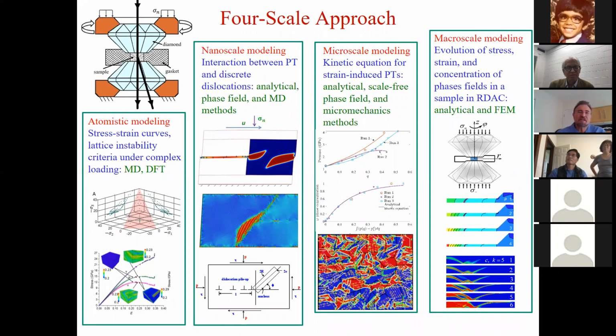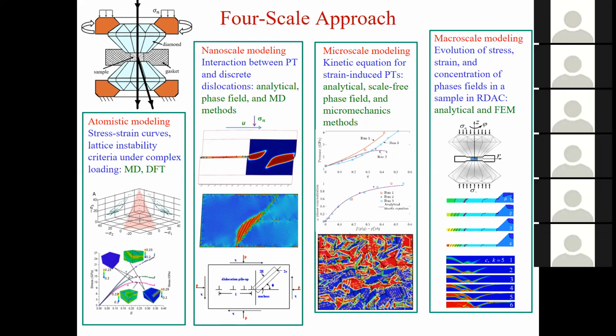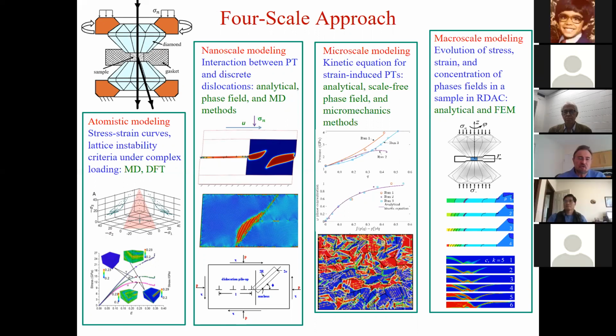Also there are collective effects of dislocation pile-up. This can be shear bands. For example, strain-induced phase transition in TRIP steel occurs at the intersection of shear bands. The transformed region at this intersection has a characteristic size of 100 nanometers, 200 nanometers. But this is not a single dislocation pile-up, it's a shear band, it can be an intersection of twins. It can also be kilometer size in geophysical scale.